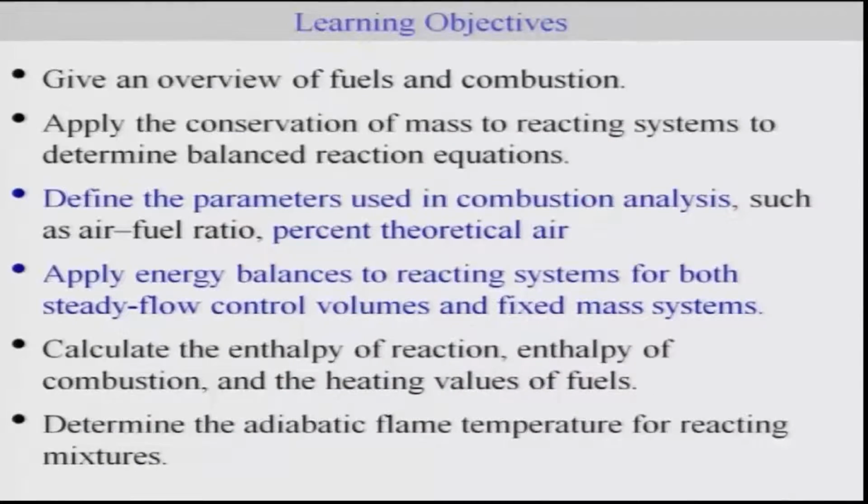Welcome back. So we were discussing the chemical reaction, and in the last lecture we went through the definition of air-fuel ratio, as well as discussed some examples of the types of fuel. We also discussed that the moles are not balanced. It's a conservation of mass balance, which we are going to make use of in order to analyze the chemical reactions for combustion processes. So in this lecture I will continue that discussion and present some of the combustion analysis,